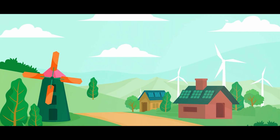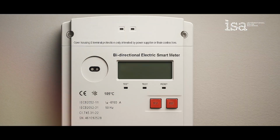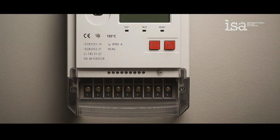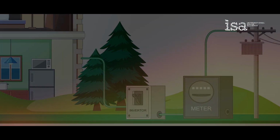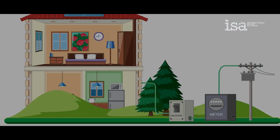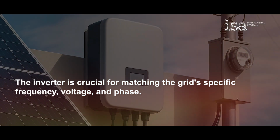Grid-tied DRE systems allow a bidirectional flow of energy. Key components like the DC to AC inverter and smart/bidirectional meter, etc., and standards facilitate this process safely and efficiently. DC to AC inverter: solar panels produce direct current, DC, which an inverter converts into the alternating current, AC, used by the electrical grid. The inverter is crucial for matching the grid's specific frequency, voltage, and phase.